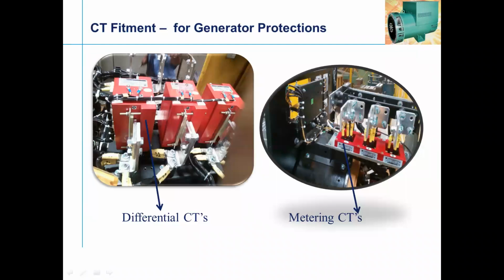So coming to the protection part which I was mentioning on the generator, where the CT, the current transformer, is very important, and the capacity of the CT is very, very judiciously required. Most of the time, the people who buy the generator miss the protection part, which is very predominant. We buy a generator for lakhs of investment, but protection is compromised.